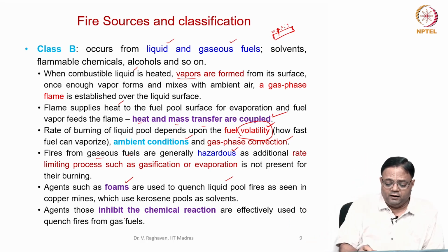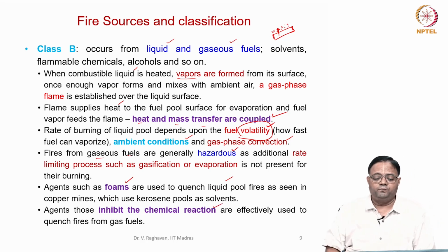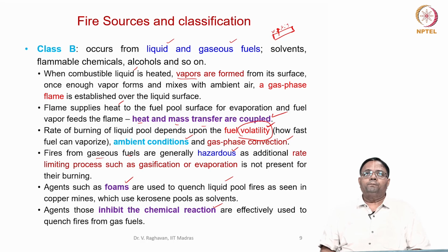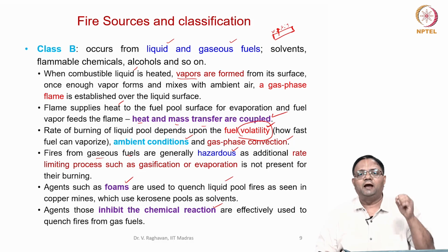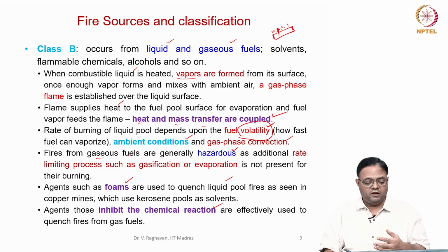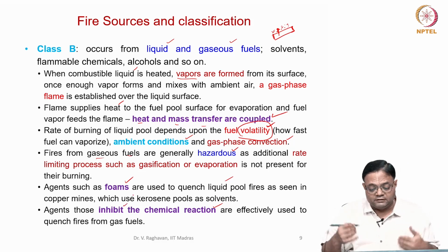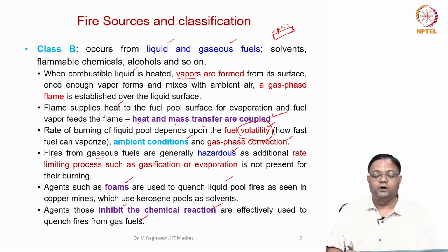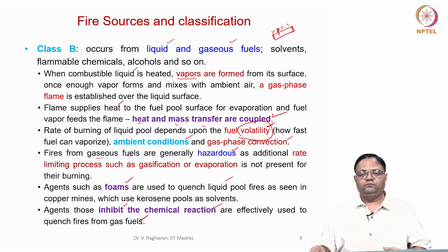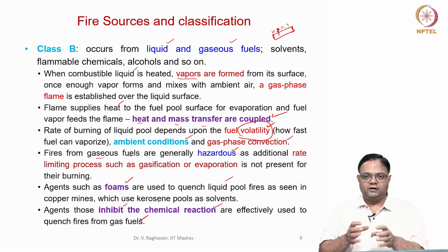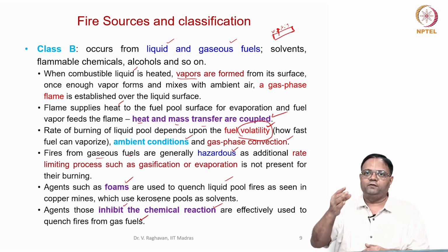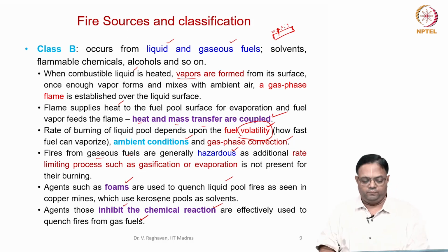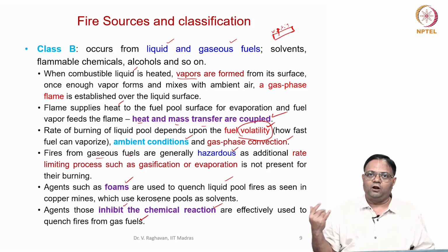Okay, now what to do for gaseous fuels? You can also use water to some extent, but if you have some agents or suppressants which will inhibit the chemical reaction itself, then that will be the best for quenching fires from gas fuels. For example, if I have some halon injected, then the halon can directly participate in the reaction mechanism and quench the fire. We'll see about this later in the last chapter.